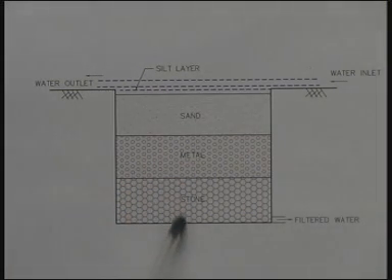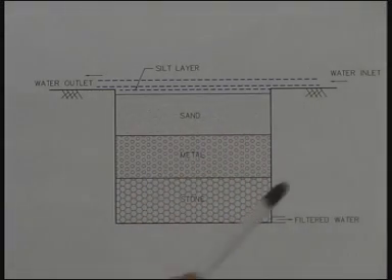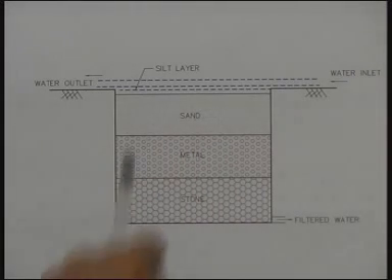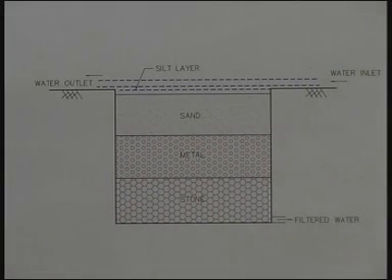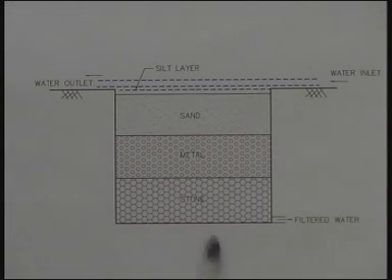The amount of infiltration rate per square meter of the bed, if supposing it is 0.5 liters or 0.3 liters per square meter per second, then even if we construct a bed of 5 meters length, it works out to about 1.5 liters per second or 2.5 liters per second as infiltration rate, assuming that the soils are capable of taking that infiltration rate coming through the sandy bed.